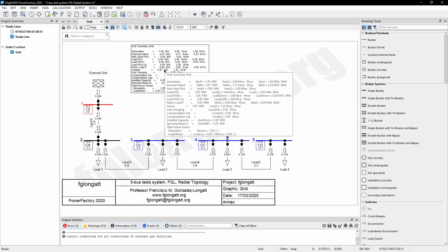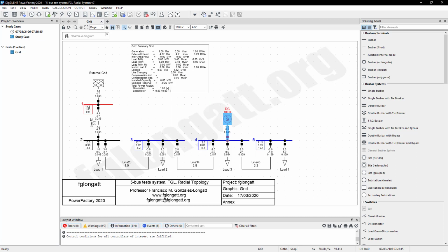Now, I believe you can see something quite interesting. You can see that the total active power losses move from 0.09 megawatts to 0.07 megawatts. What I'm trying to say is that using local generation installed close to the demand, or what we call DG, is especially positive for the distribution system if we have the appropriate control and the appropriate operating mode for those machines, okay? Well, I think that is all for today.